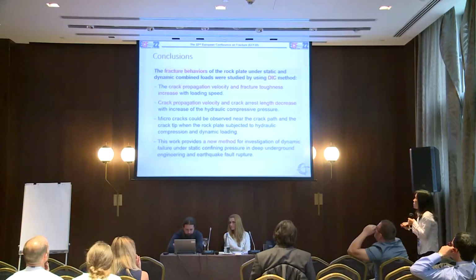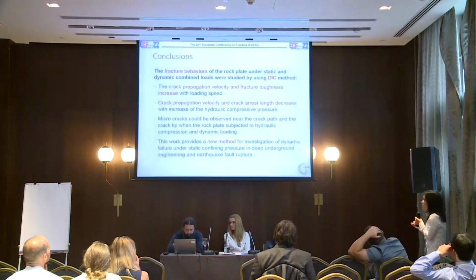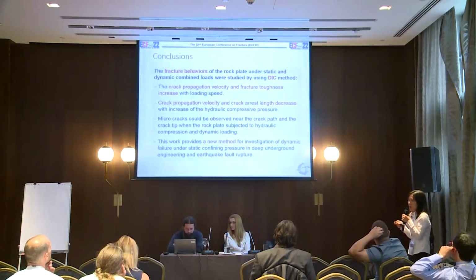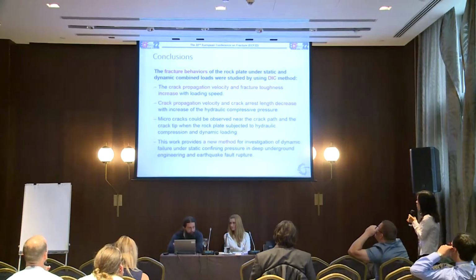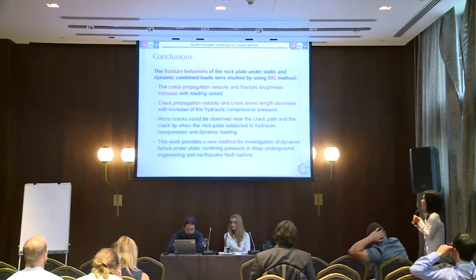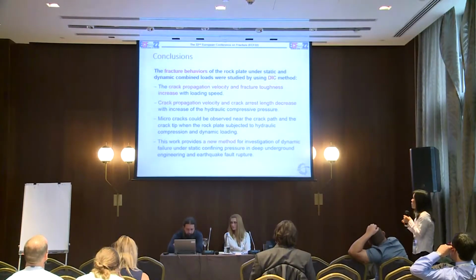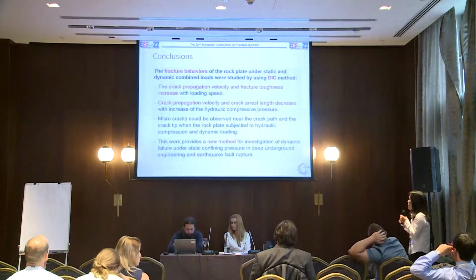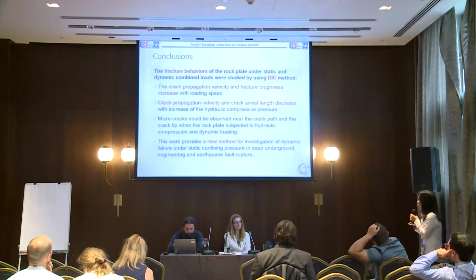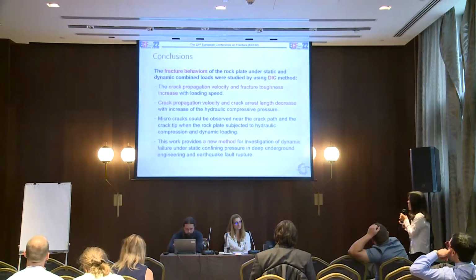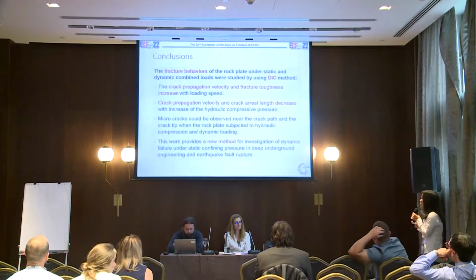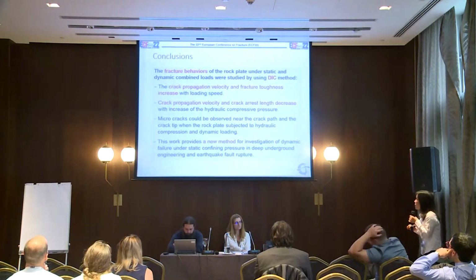Conclusions. By using the digital image correlation method combined with the ultra-high-speed camera, we get the fracture behavior of the rock plate under static and dynamic combined loads. The crack propagation velocity and fracture toughness increase with loading speed. The crack propagation velocity and the crack arrest length decrease with increase of the hydraulic compression pressure.